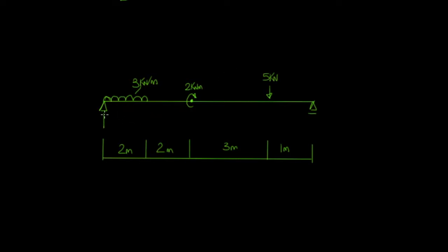So we know this beam is simply supported. There's three reactions. We'll call this side A, where we've got reaction AY, and at B, we've got reaction BY, and we also have a horizontal reaction at A, which will be known as AX. So this beam's in equilibrium because it's one member and we have three reactions in total. So we know that the sum of our reaction forces is equal to 0.